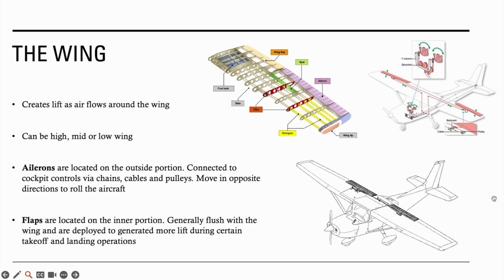On that note as well, since they are electric, if you do have an electrical failure in the aircraft, you just won't be able to use your flaps. Not necessarily an emergency. You're going to train how to land without flaps. Flaps just help you. It's not a requirement to land with flaps every time. In my experience, most people have better landings without flaps than they do with flaps. So you might notice that as well.